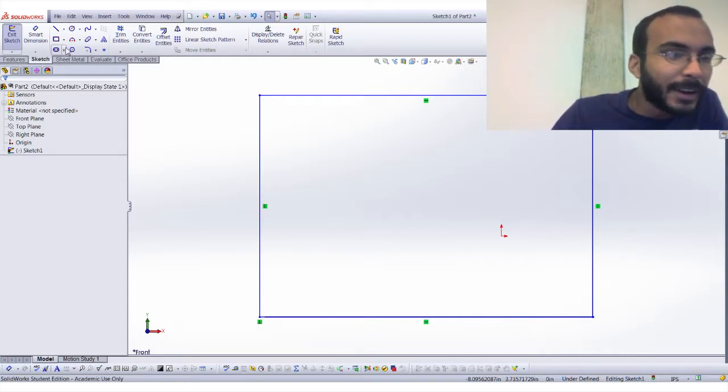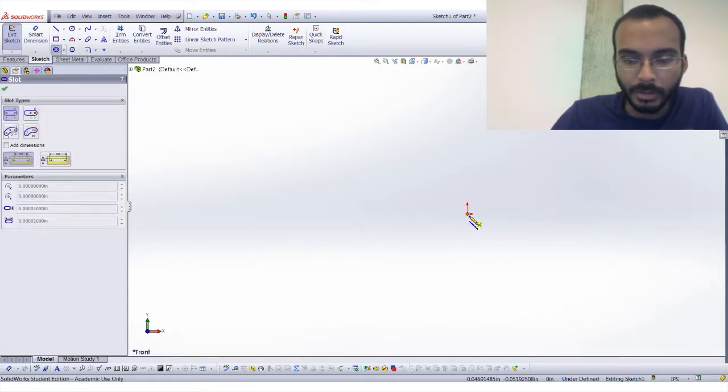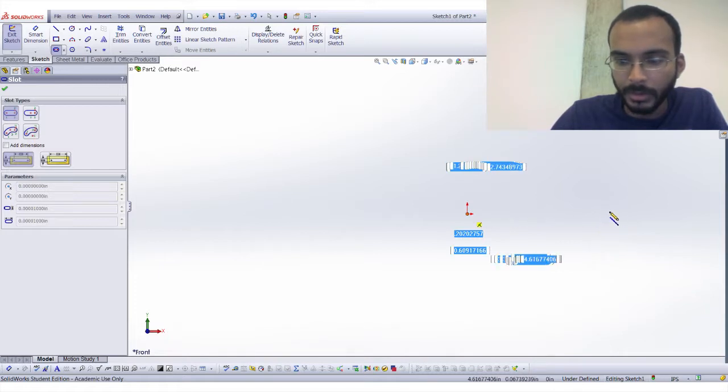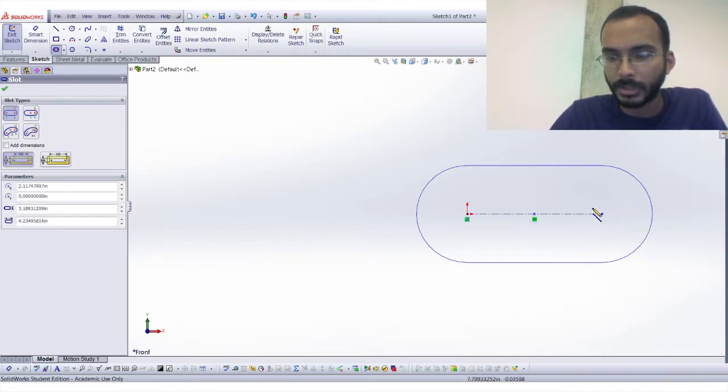Thank you very much. Okay, so a couple other things we haven't seen. So we saw circle, we saw line, and we saw rectangle. Straight slot basically just does 2 circles, but it connects them together with a line, so you tell it how big the slot's going to be, and then you can give it a diameter out this way. So you can very quickly draw a slot.